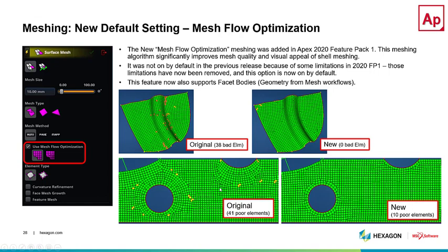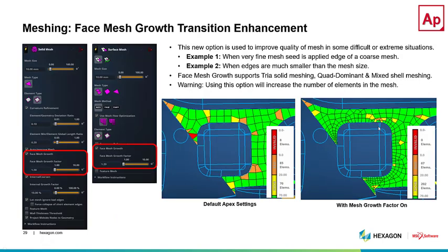And then you can see another example here where the washer mesh just turns into something that is more along the lines of what you would originally want as your completed, nice, finished mesh. Also look at the nice, clean edge mesh of one layer of elements that follow the curvature of the part as opposed to all of this kind of nonsense happening over here. So overall, you just get a better mesh.